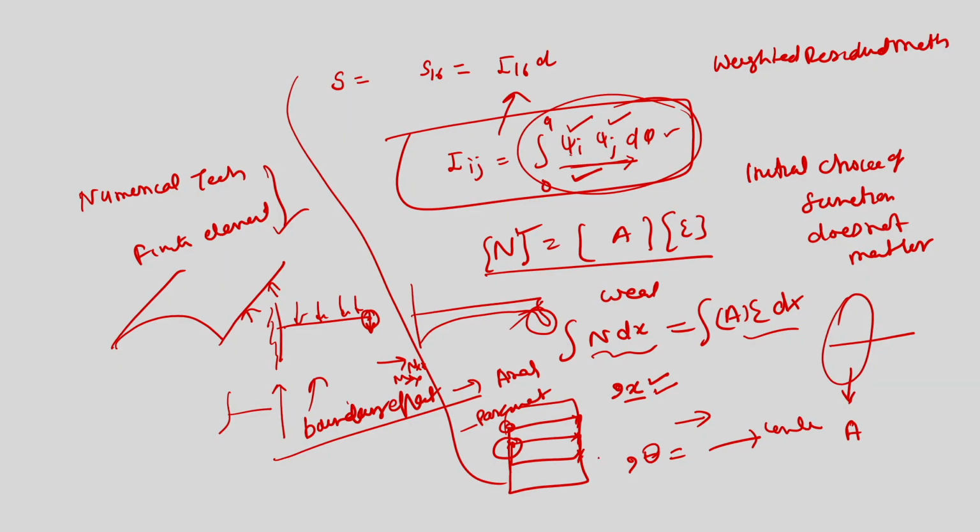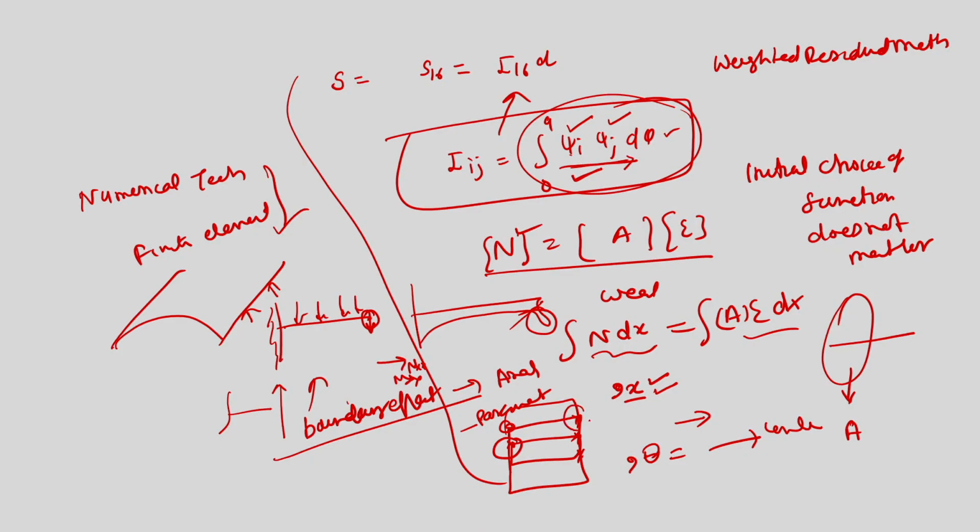In composites, this is the most prominent problem that we are trying to overcome, or to understand, what level of stresses are shooting in this area. If this edge is free, then at the very edge the stress needs to be 0, but just near the edge it is very high. So, we are interested in finding what causes delamination in composite shells.